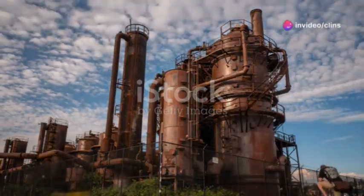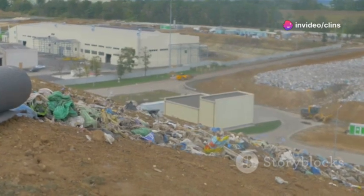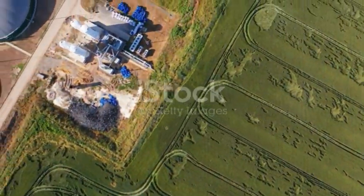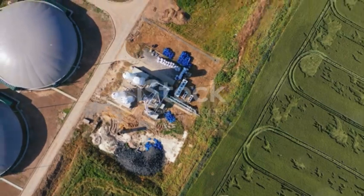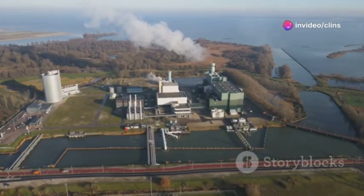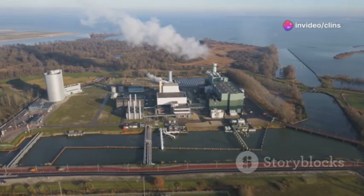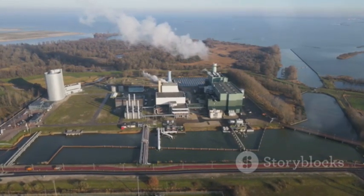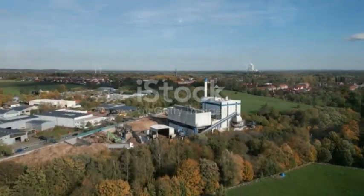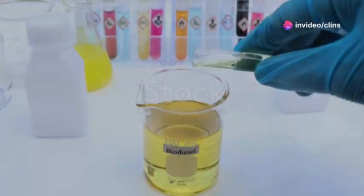Finally, gasification. The principle here is converting biomass into syngas, which is a mixture of carbon monoxide, hydrogen, and methane, at high temperatures between 800 and 1000 degrees Celsius with a controlled amount of oxygen or steam. The process involves heating biomass in a gasifier, producing syngas, which can be cleaned and used to generate electricity, produce heat, or as a feedstock for chemical production. Applications include power generation, chemical synthesis, and hydrogen production.